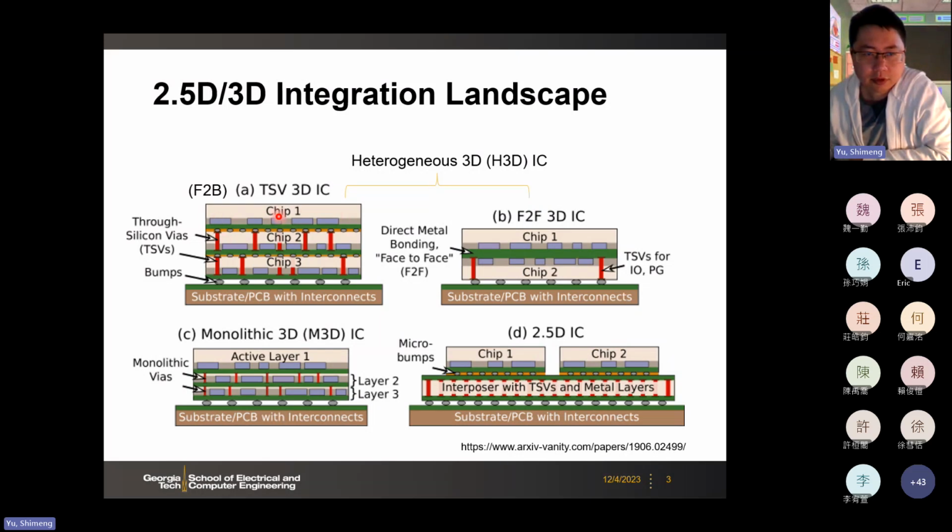Those chips are DRAM dies, and this will feature high bandwidth, because we have multiple connections between the DRAM's I/O. So we would have a wide I/O. Here then the DRAM's TSV and bump, this bump being a micro bump. Those will be the foundation for today's HBM.